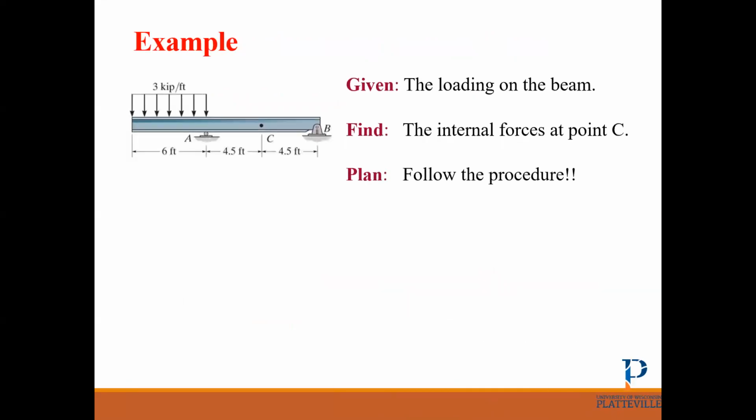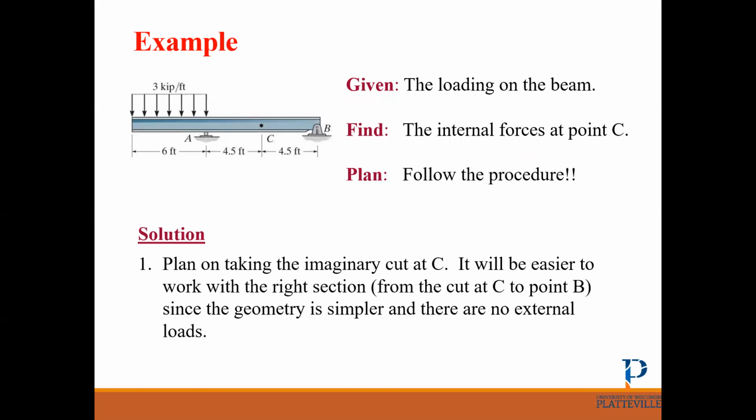All right, so this is the problem. The loading on the beam is given. The internal force at point C is something we need to find. Follow the procedure. To do this, first plan to take the imaginary cut at C. So it's very obvious, we want to know the internal force at C.